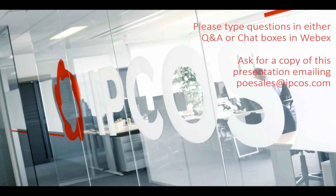Or if the analyzer is just, per se, not that reliable technology, then that is also something that you need to think about. If you know that your analyzer tends to drift with time, there you go. If your analyzer needs to be maintained very often, same thing. So the answer to the question is not a single one. It just depends on the situation.